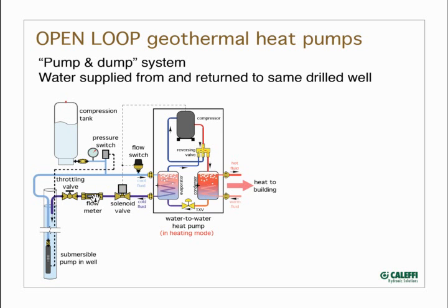The second keyword is quality, water quality. The only way that I would consider safe doing one of these systems is to have a water quality test done by a professional water testing lab, know exactly what's in that water, and then verify with the heat pump manufacturer that those levels of whatever is in that water are within acceptable levels from that manufacturer such that that water can go directly through the heat pump.